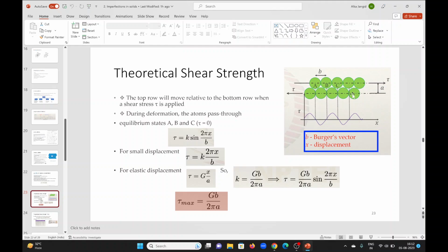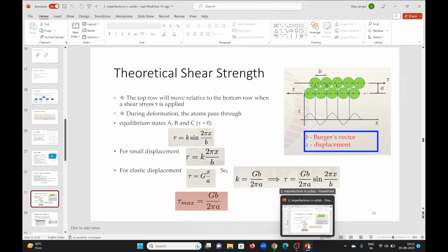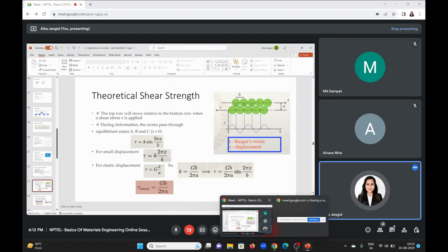So for example, if you have a copper nickel system and you are performing XRD on that, you'll get copper peaks and nickel peaks. By that you can tell that this system has copper and nickel. If a different phase is also present, there will be different peaks for that phase, and from those peaks you can understand what types of phases are present in your material.